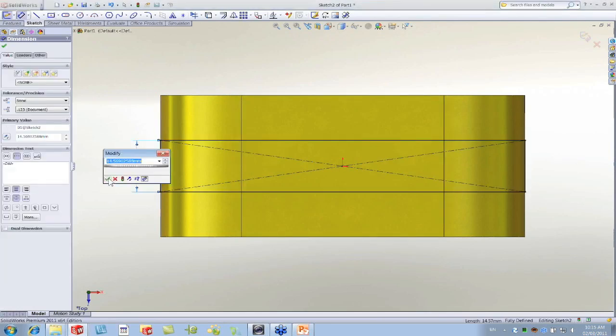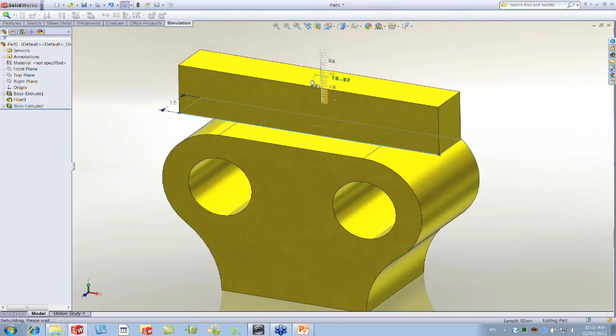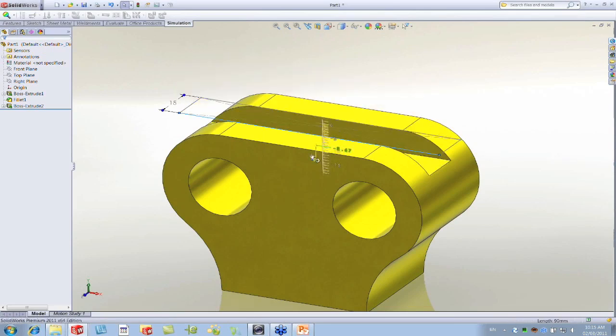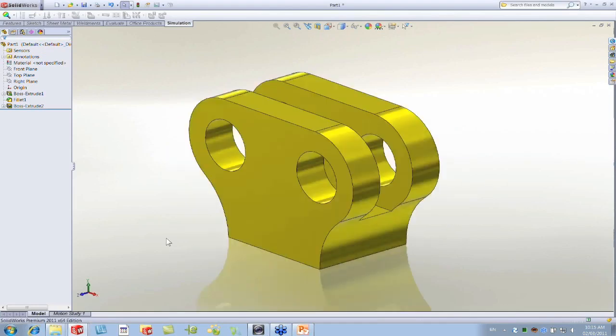There we go. Now, as I was saying, this is only a 2D profile. Now I want to extrude this. As I've done earlier, I can simply select the profile. Pulling outward, SolidWorks will detect that I want to add material. But if I start going the other way and pull inward, SolidWorks is going to detect I want to remove some material. So I'm going to drop this maybe to minus 40 and drop it over here. So now I actually opened up a slot.